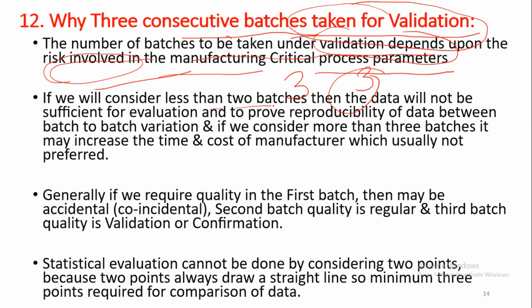If we consider less than two batches, try to understand here, then the data will not be sufficient for evaluation. If we take less than two, the data will not be sufficient to prove reproducibility, the batch to batch variation. And if we consider more than three batches, it may increase the time and cost of manufacture, which may not be preferred.